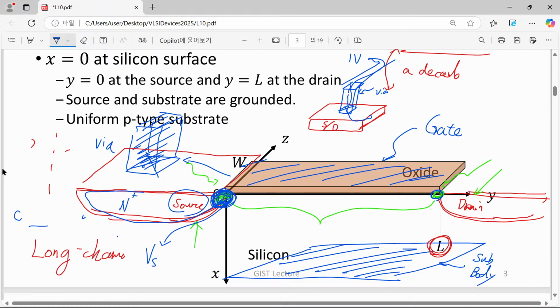And here we have the opposite end attached to the drain, and we will say the quasi-Fermi potential at that point, the drain end, is regarded as simply the drain voltage. This means that if you apply 1.0 volt to your drain, then the quasi-Fermi potential at this point is also set to be 1.0 volt. There is no voltage drop between your external drain and your internal drain.